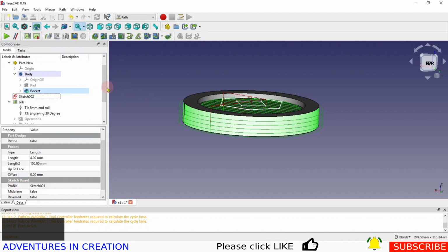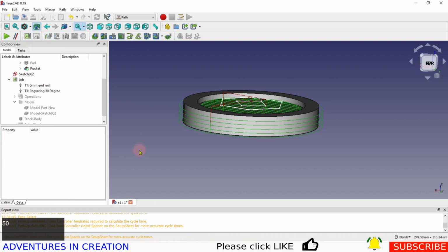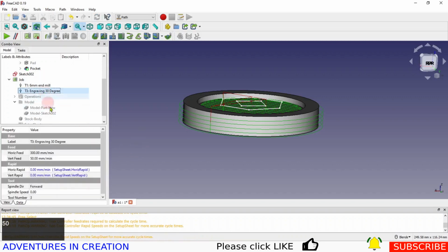Now, one thing, if you haven't already included it in the tool, is we want to make sure we have our feeds and speeds set up. So for engraving, I normally go at 300 millimeters per minute. And for the vertical feed, that horizontal feed means that's basically how it's cutting. The vertical feed means how it's dropping down and how many times it's going to drop down. I usually drop down slowly because I don't want it to plunge hard on a point. So I'll drop down at 50. So that will be my feeds.